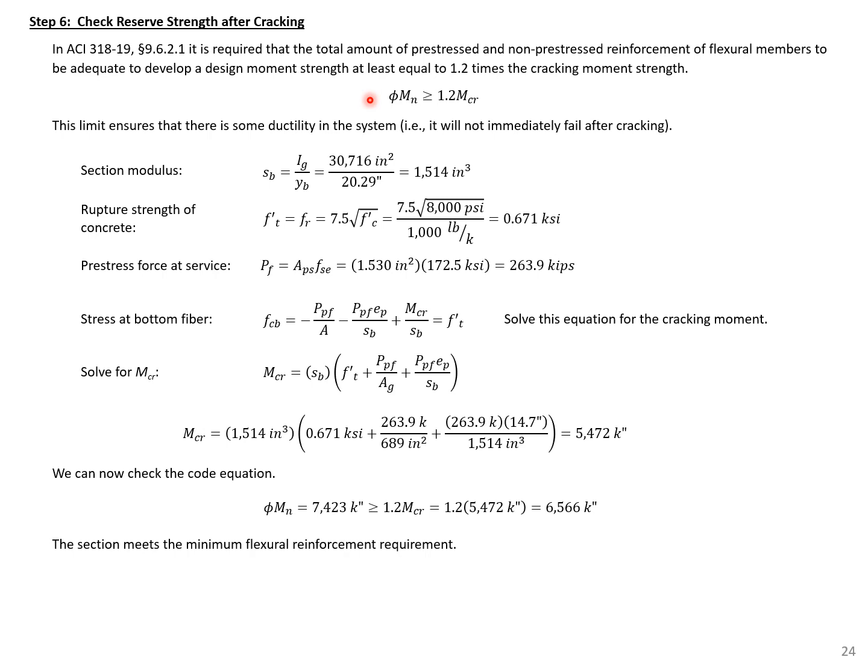Our pre-stress members are designed to have a much higher cracking moment than typical reinforced concrete members, so this limit will sometimes control our design.